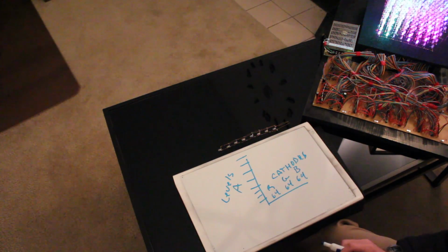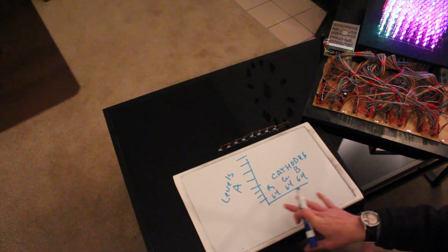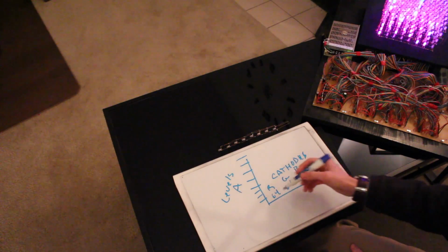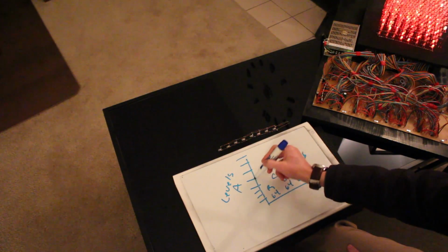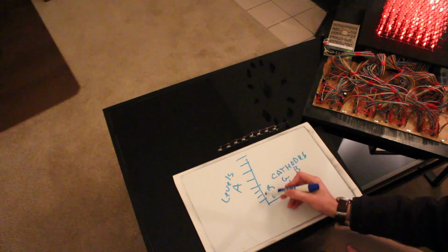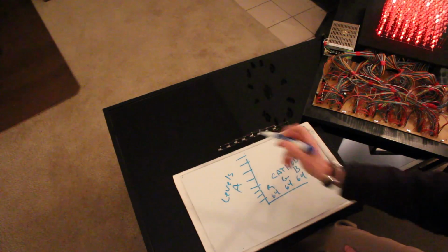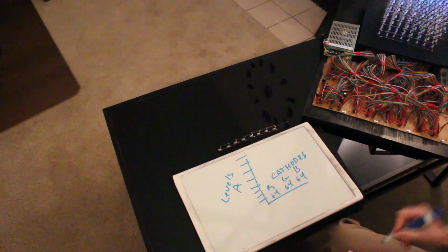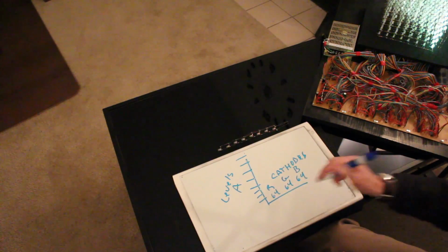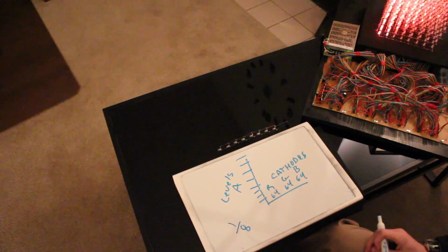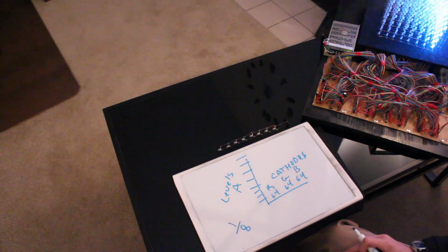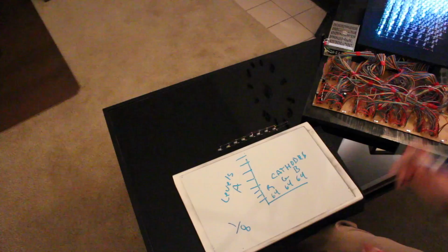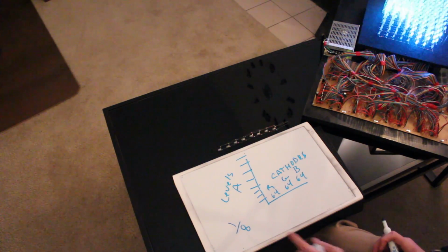It's the same thing as the 4x4 grid I just talked about, but what this should tell you is that each level is multiplexed. So what I'm doing is turning each level on, and each level has a single chance to turn on. So the duty cycle of every single LED in this cube, the max it could be on for, is 1 out of 8. So it's actually worse than that other example. It's not too good, but you'd be surprised. You can get some pretty decent brightness out of that. So 1 out of 8.